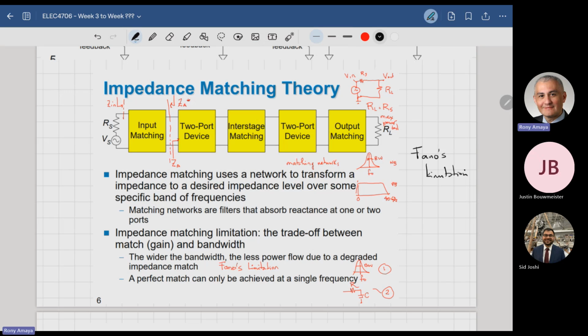So what is the purpose of a matching circuit? You've got left, you've got right, and you put an impedance matching circuit in the middle. What is the main purpose of it, at a high level? Yes, but what are we doing to the two of them? You go to the guy on the left and say, what do you need? I would like to see this impedance to be able to give you maximum power transfer. And then you go to the guy on the right and say, what do you need?